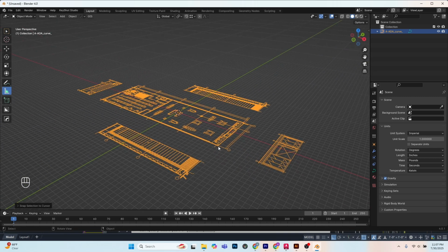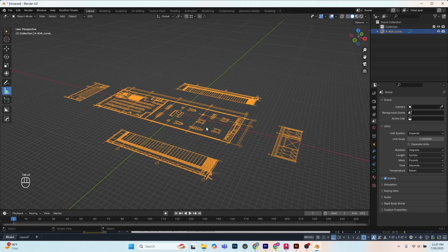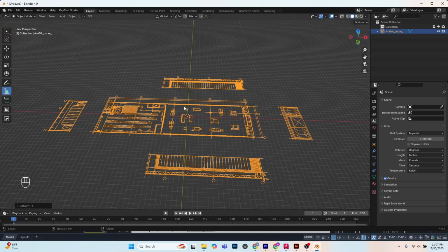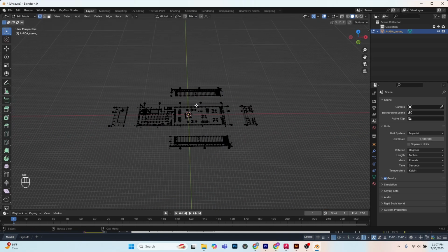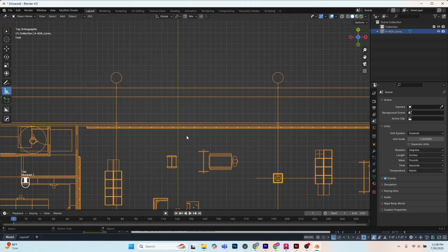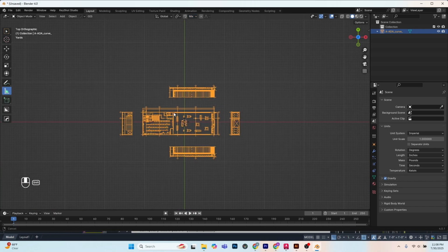And so now I have my AutoCAD file set up as inches imported into a Blender scene that's using inches. So again, I'm going to convert this into a mesh, enable multiple vertex, edge, and face selections by shift left clicking, tab into edit mode. Now I can grab individual edges and vertexes, and the snaps work. So now I have my snaps as well.